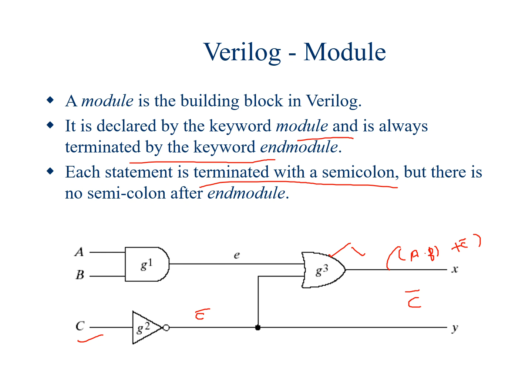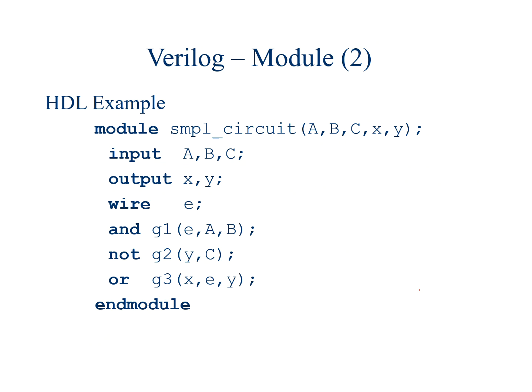So now we are going to write the Verilog code for this combinational or Boolean expression, that is, for the logic diagram. The module name can be any name. The inputs are A, B, C, and the outputs are X and Y. Hence, end with a semicolon. And then the inputs A, B, C are declared and end with a semicolon, and the outputs are X and Y.